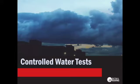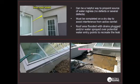So controlled water tests. These can be beneficial, again, if no defects were uncovered during the investigation. It can also be if there were a number of defects and we want to pinpoint which defect is contributing to the leak. That could be maybe your board doesn't have the budget to complete all the recommended repairs. So we want to diagnose which ones are currently contributing to the leak and address those to start.